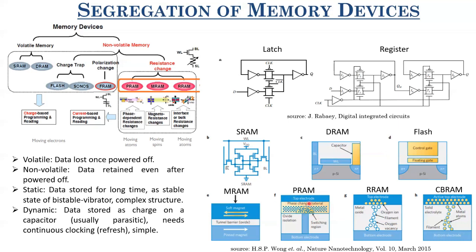Now, what exactly happens here is we heat this phase change material. How can we heat it? We do not have a heater inside your chip. What we do is we pass a current through this phase change material between bottom electrode and top electrode. Because of this current, Joule heating is created, right? So we apply a short pulse of current to create Joule heating. This Joule heating melts the phase change material. Now the best part about phase change material is that it exists in two stable states. One is crystalline state where its resistance is smaller. One is amorphous state where its resistance is large.